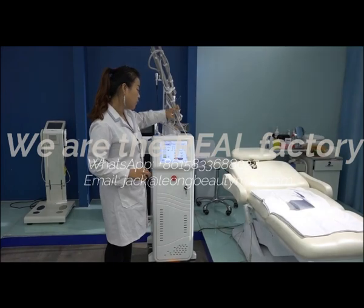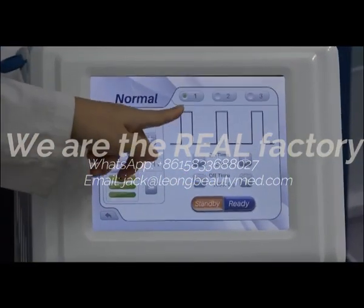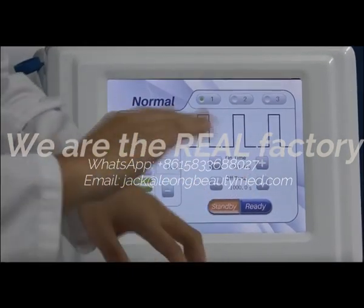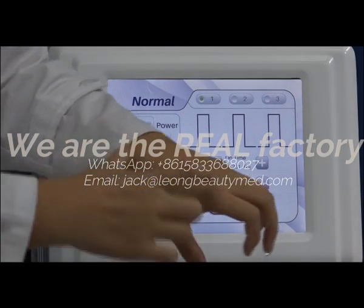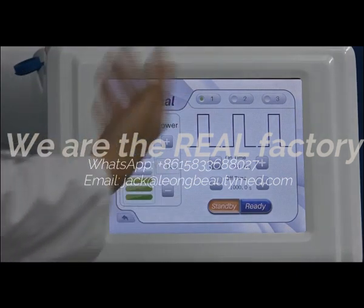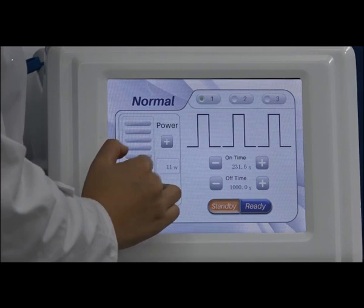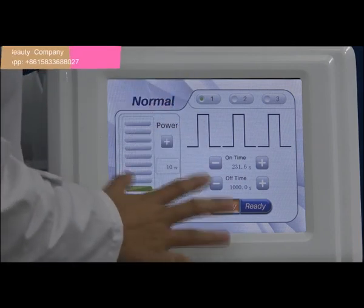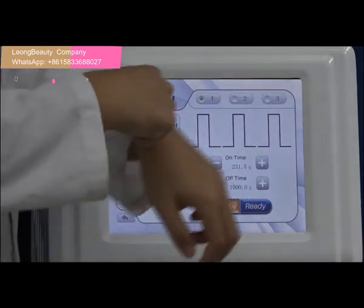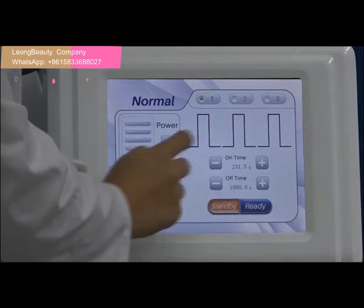There are 3 modes for cutting. The first mode is pulse mode, meaning working, stop. This is not continuous. So if you do the area not continuously, you can use this one. This one is more safe. Normally we set the energy from 10 to start. Then on time and off time you can set according to your speed. It's okay. Ready, working is okay.